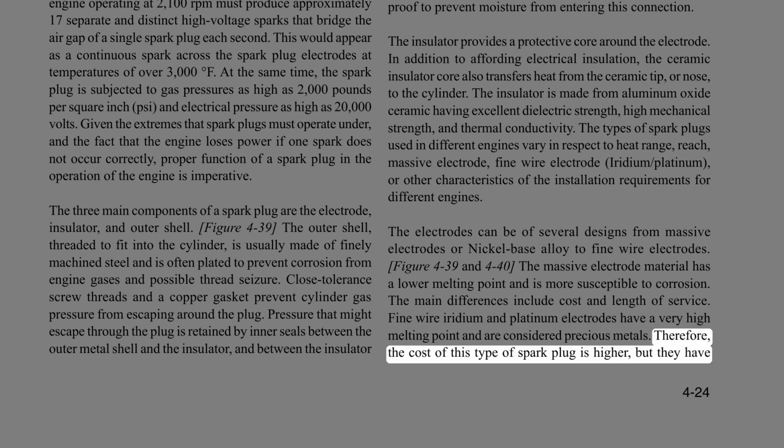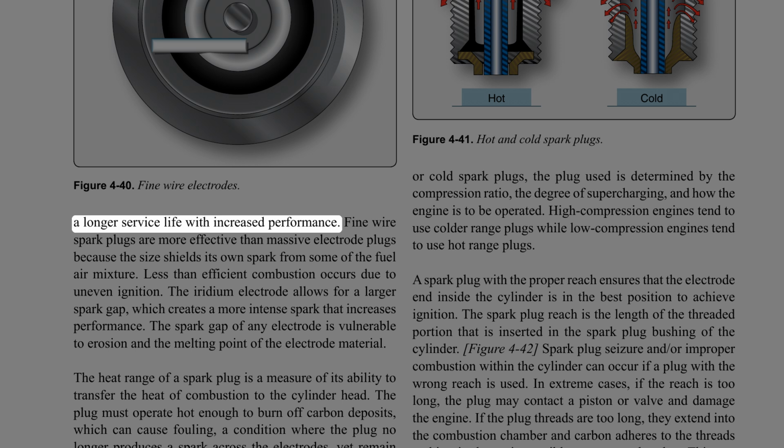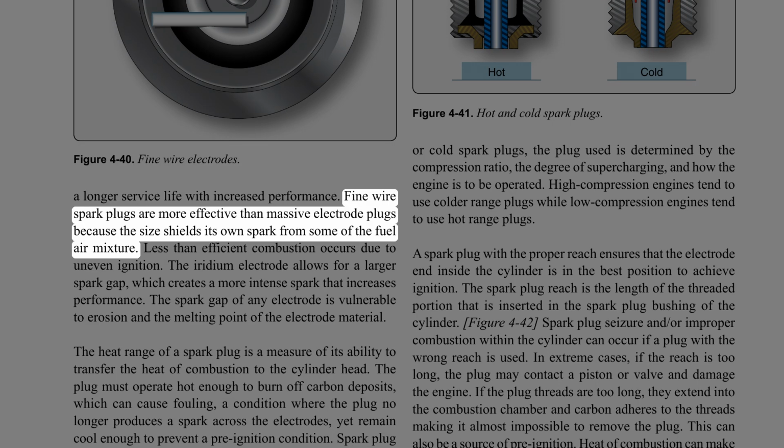Therefore, the cost of this type of spark plug is higher, but they have a longer service life with increased performance. Fine wire spark plugs are more effective than massive electrode plugs because the size shields its own spark from some of the fuel air mixture.